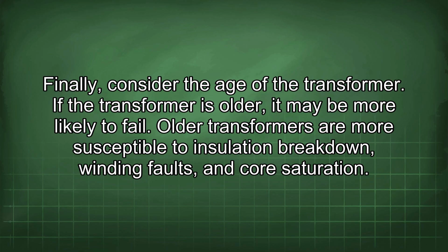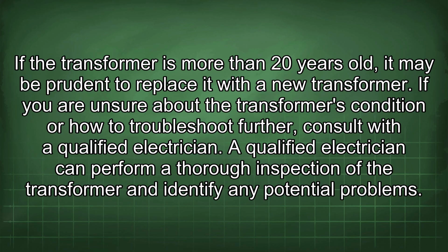If the transformer is older, it may be more likely to fail. Older transformers are more susceptible to insulation breakdown, winding faults, and core saturation. If the transformer is more than 20 years old, it may be prudent to replace it with a new transformer.